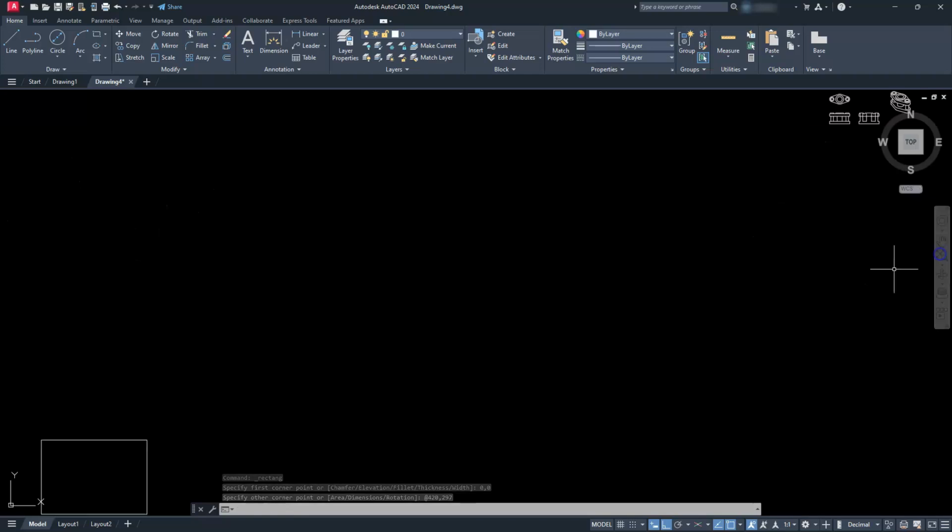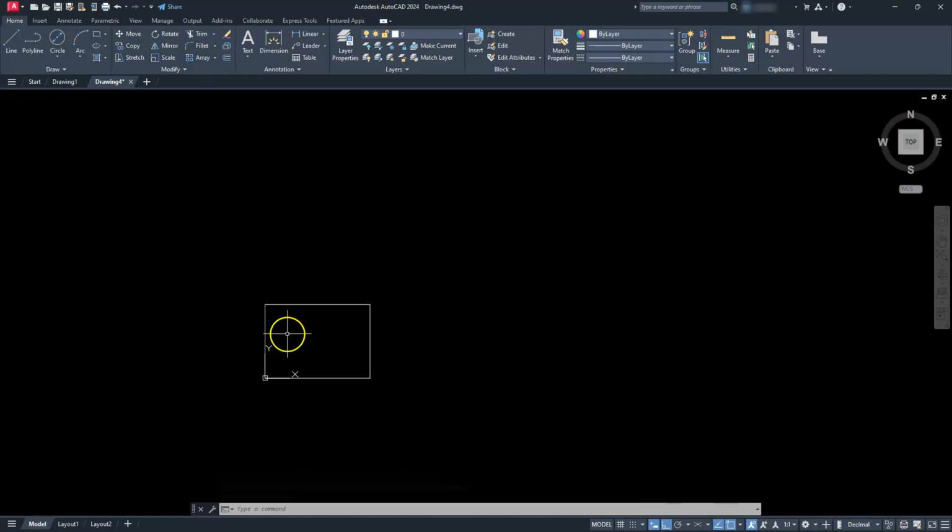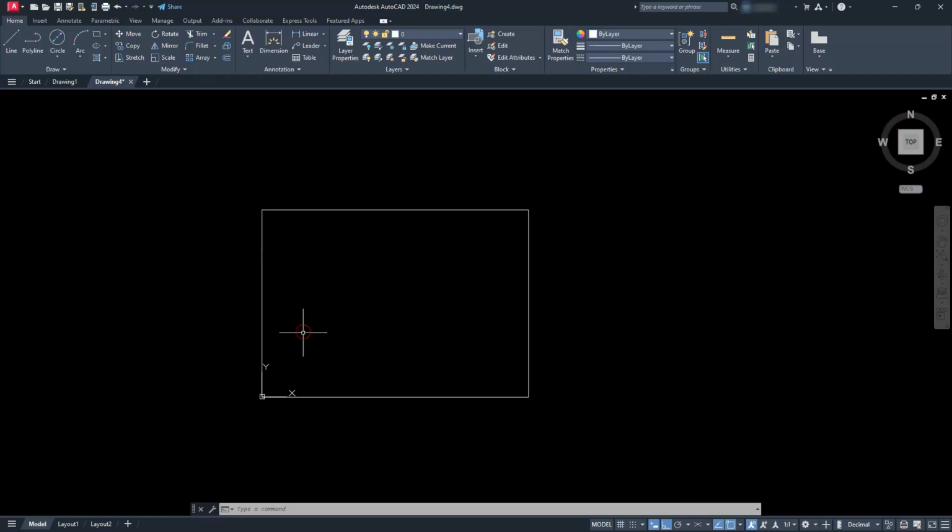So let's go find out where that's at. Let's go ahead and hit the zoom extents again. And you can see here's my A3 size title block. And this is where things get a little bit different, right? We're going to have to start thinking in metric. So this is when I used to go ahead and offset 0.25, but we have to think metrically, right? So 0.25 times 25.4, which happens to be the magic number to convert things from inches to millimeters, right?